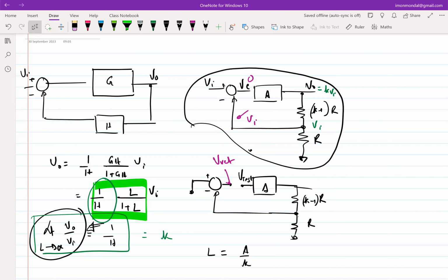So let's say I inject something here, right? If I inject something here, what's going to happen? If the loop gain is high, then this guy and this guy will track each other, which means output will be as is. If the output is as is, this guy shouldn't move, isn't it? Which means even if I inject a current, the voltage shouldn't move. Right? The loop should always correct. That's why there is a loop. The loop corrects any excursions anywhere.